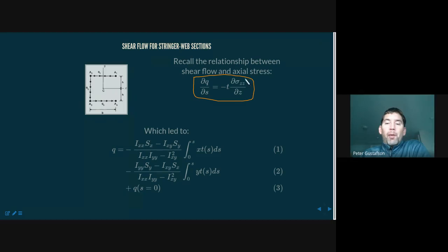Okay, so this is more of a bending stress over here, sigma zz. Its derivative then leads to this shear that's present in the structure, and that's ultimately because shear and bending are related, not the same, but related, and that's how this equation came about. And then we had taken this equation and we plugged in our known values for beam bending stresses, and that led us to this version of the equation, which at this point seems rather lengthy, but you actually saw that it's fairly easy to understand once you get the hang of it.